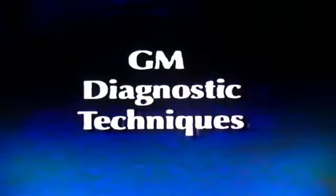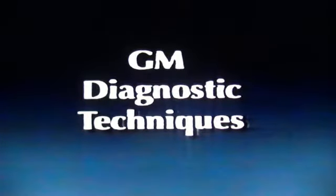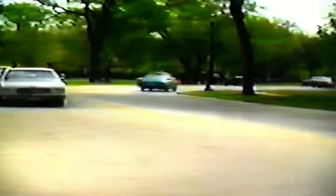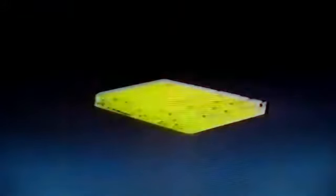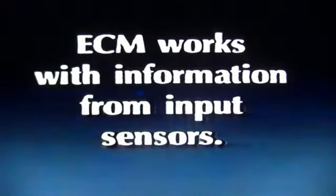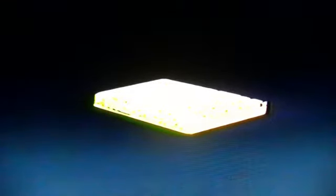This tape, we'll be finishing up our discussion of the field-tested diagnostic procedure. The last area we'll be covering is how to make sure all the various components of the 3C system are operating in acceptable ranges. Remember, any improperly functioning sensor can provide the computer with inaccurate information. That's why the ECM can only work as well as the information it gets. It doesn't have the intelligence, not yet anyway, to decide which data is correct and which is false.